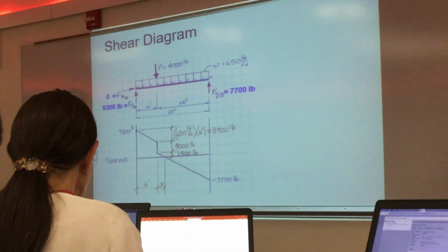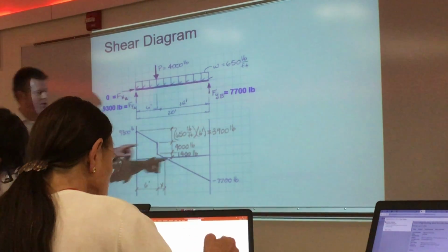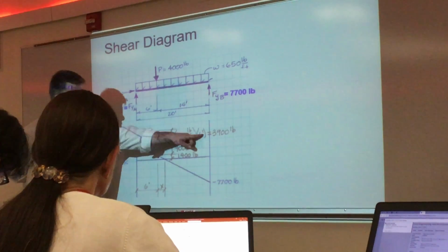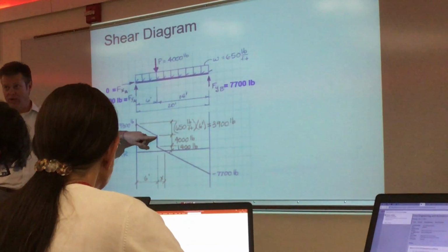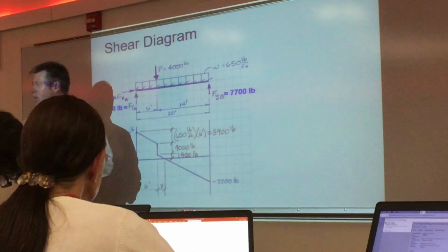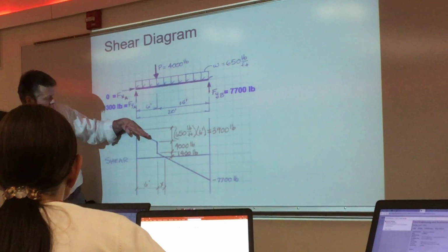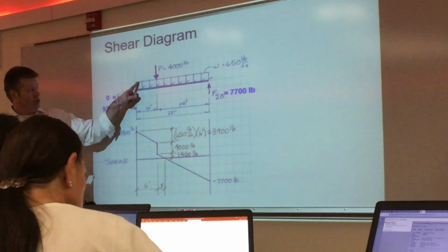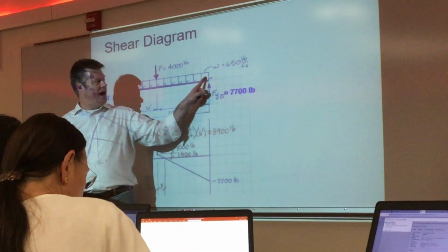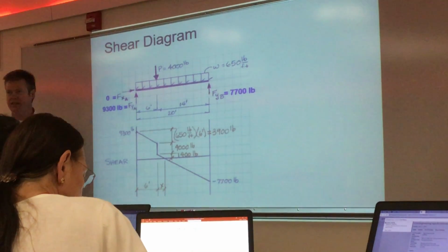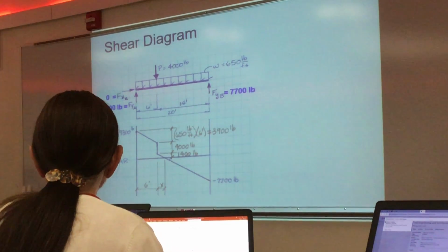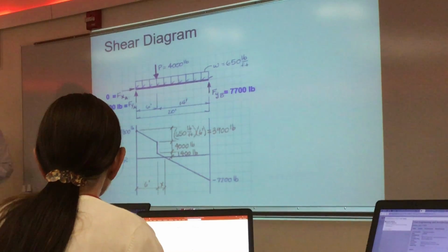Trying to figure out in my head, I think that 650 times 6 is just the 3,900, and that's just the height that is changing. So 9,300 minus 3,900 equals the value at that point. Yep, the 650 pounds per foot is the slope of that line. So here's your real math connection. This magnitude that they show here is the slope of the next diagram. If you really want to blow their minds, you could say, hey, that's calculus. That's actually what that is.